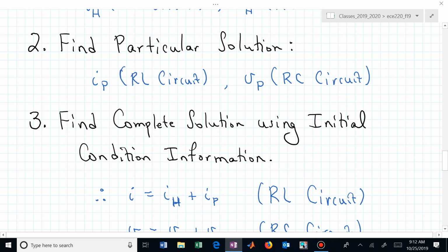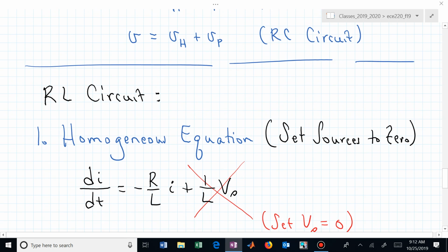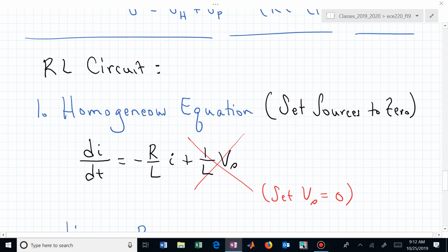And eventually then just find, by inspection of our circuit, what the initial condition is on that state variable, what the final value is on that state variable, and what's the time constant to provide us with the exponential structure. Let's work through that now, and then we will use this in our toolkit, but we won't necessarily have to always rederive this as we go through it.